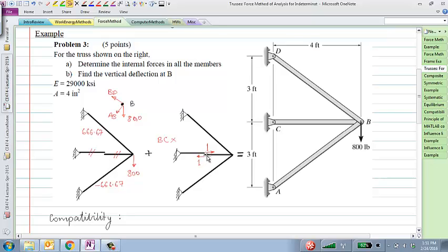And once again, with this unit load, if you calculate the internal forces, we will get minus 5/8 compression in this leg, minus 5/8 compression in this leg, and these 2 separate pieces would also be in tension in the amount of 1. So that's an important thing for trusses that we need to keep in mind. This would be 1, this would be 1. Okay, so we've done the underlying determinate structure and the determinate structure subject to a redundant force.